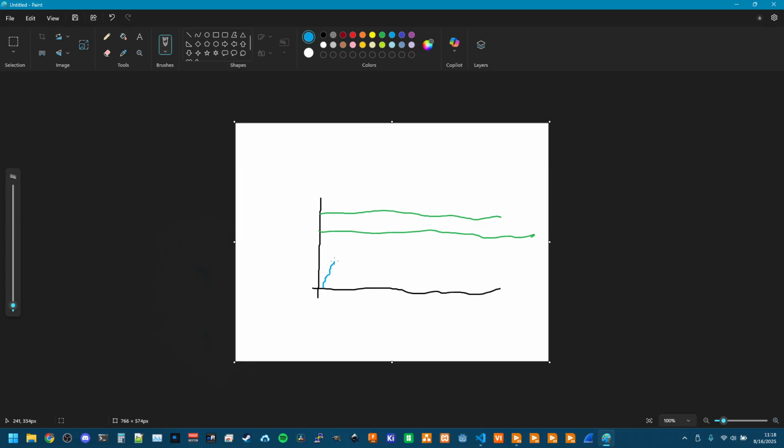So you want the process to increase till it hits the upper limit, and then you're going to change some output value that's going to change it. Maybe it still overshoots a little, but then it comes down, and when it reaches the lower limit, you're turning something back on. Or maybe it's the opposite. Maybe you have something turned off until it reaches the upper value and then turns on when it gets, or did I say that backwards? Yeah. Turns on to bring it down.